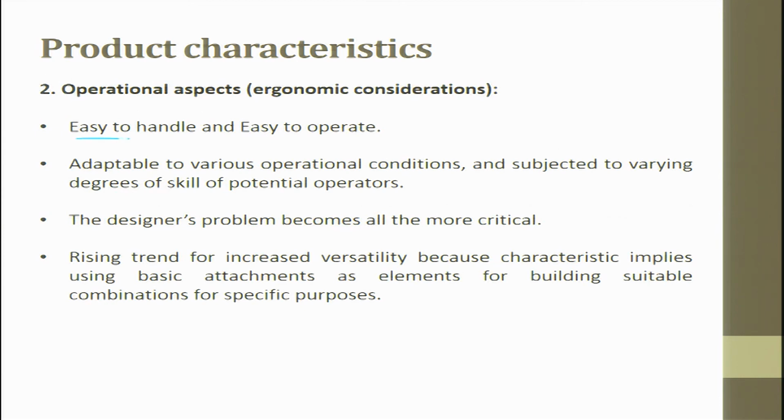The operation, easy to handle and easy to operate. Adaptability to various operational conditions. Many a times the AC whatever we buy in India, they conk off when the temperature goes above 48 degrees or 47 degrees, because there is too much heat generation in the compressor side. The heat in the compressor could not be extracted, so it conks off. So, until the compressor is cooled, your AC will not work.